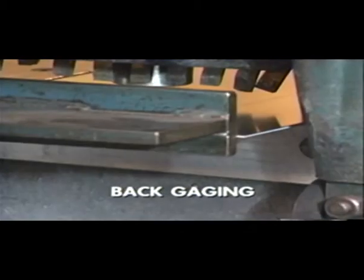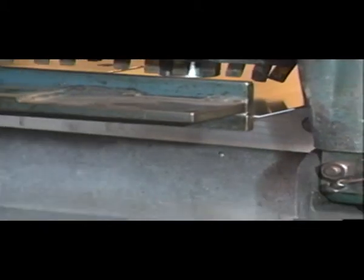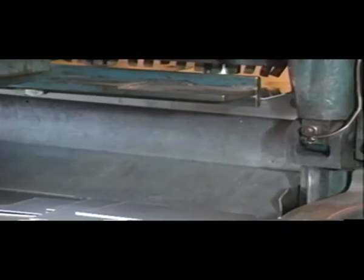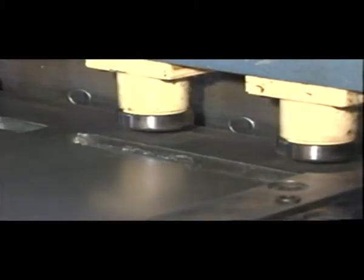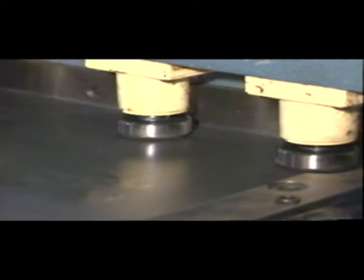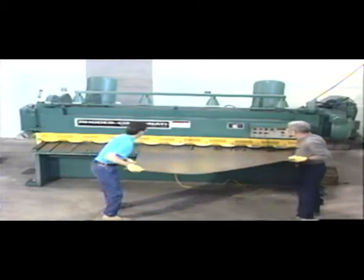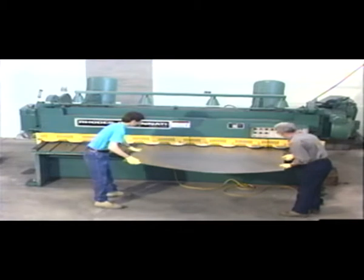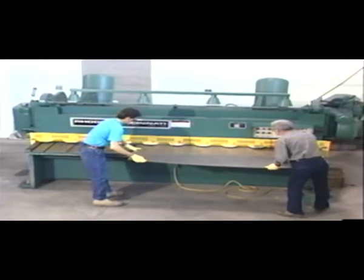In back gauging, the operator pushes the material between the knives until it comes to rest against an adjustable stop or back gauge. The material is then sheared. For rapid, accurate cutting, electronic sensors in the back gauge automatically start the shearing process only when the stock is in the correct position. When the back gauge is used to shear wide drops of thin metal, the material often sags, causing an inaccurate measurement.